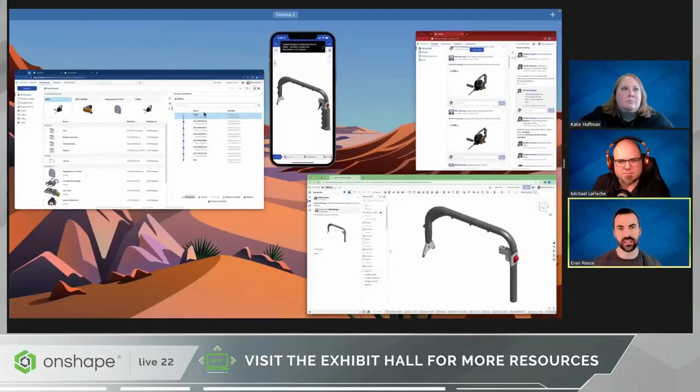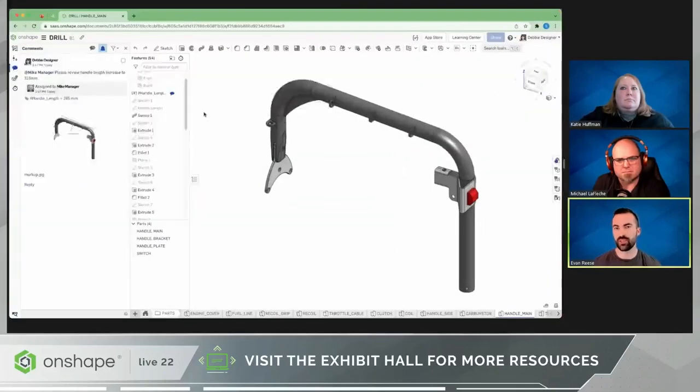Other things that we use a lot are just the way that we name features. You try to give it a sensible name, but you may not know that you can use up to 256 characters for a feature name. You won't be able to see it all, but if you mouse over it, you'll see it. So if it's a certain situation and I'm using a feature and it's not clear why that feature might be there, I might use a whole paragraph of text to say, this feature is here so that the next feature doesn't fail because it was failing or something like that. And that's a valid feature name. That actually gives a lot more information to someone that's new to the model as to why that's there and what they can change without breaking anything.